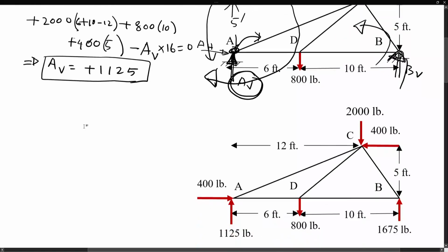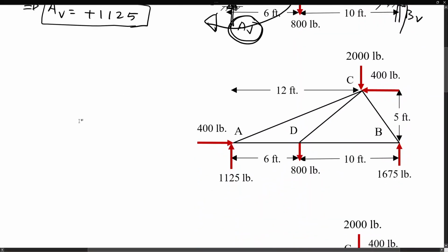Next step is the concept called the method of joints, where you only look at these joint points. These are the joints of this structure. We can look at different points. Let's look at point B only. If you look at point B, you only look at point B. There is one force carried by member BD. So this is my point B.